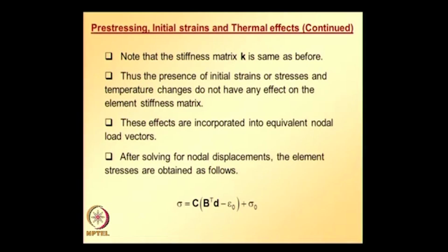Using nodal connectivity we can assemble the global equations and apply appropriate essential boundary conditions and solve for the nodal displacements and do all kinds of post processing.